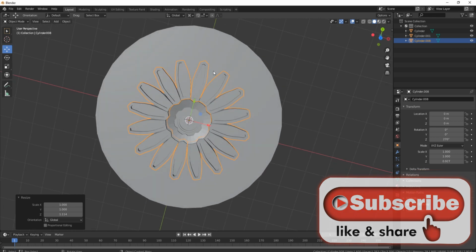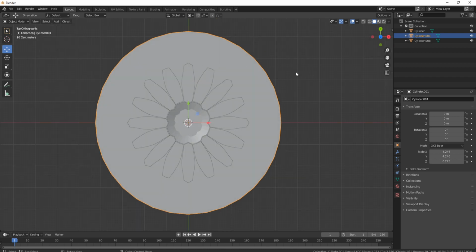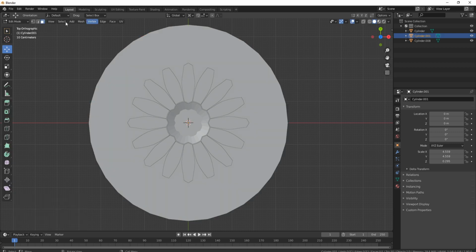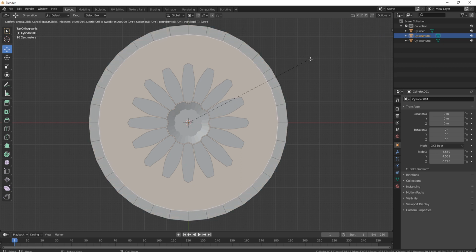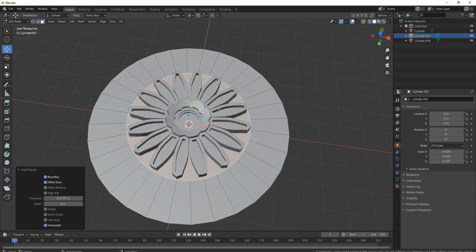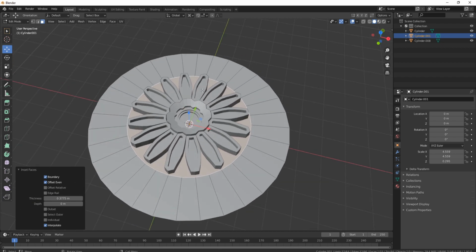Now what I want to start work on is the actual outer. So I'm going to grab our template that we made. I'm going to check if I press 7. Let's see, do I want it a little bit bigger than that? Probably so. So I'm going to press S and just pull it out a little bit. Next, I'm going to press Tab. I'm going to come in with face select, so I'm going to grab the whole thing. I'm going to press I, and what that's going to do is enable me to bring one in right up to the edge of where these are. Okay, so something like that. So this is basically going to be stone. This is going to be the stone ornate part, and then in between there is going to be the actual glass. So you can see it's probably still a little bit thick, but we'll work on that as we move along.